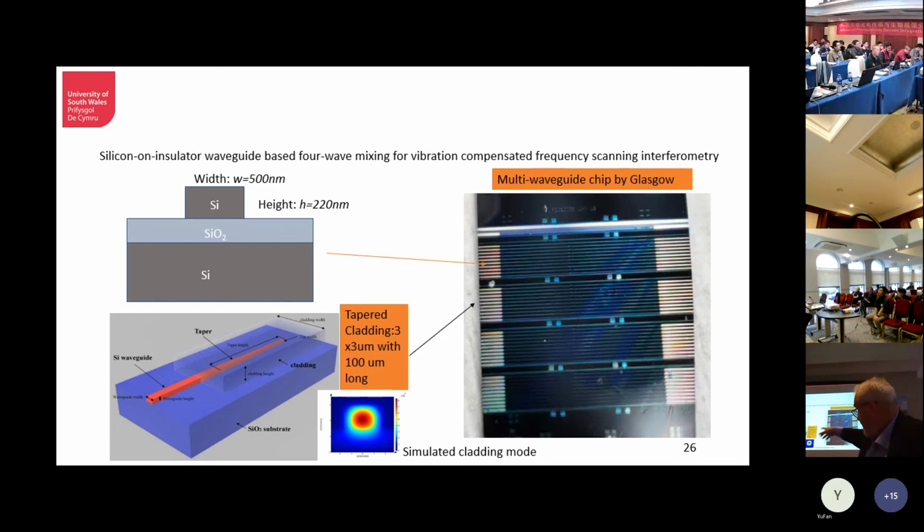And this is a technique that's very powerful. If you didn't have this, you'd probably struggle to get 5% of the light into the waveguide. When you've got that tapered overlay polymer, it actually allows you to get couplings of the order of 50% at best. So it's a big breakthrough in terms of coupling light into these types of waveguides. So it works well for that one.